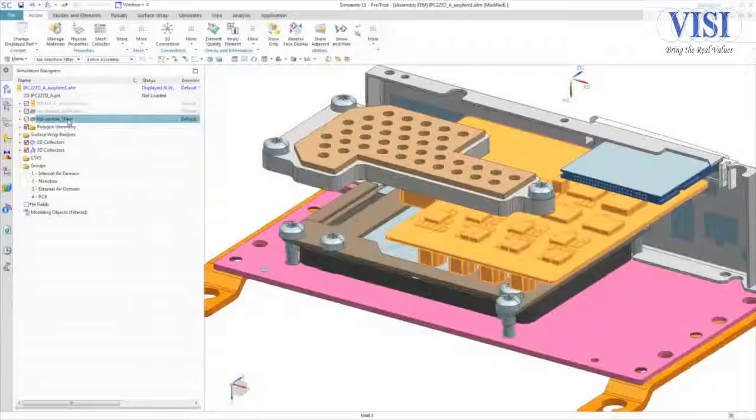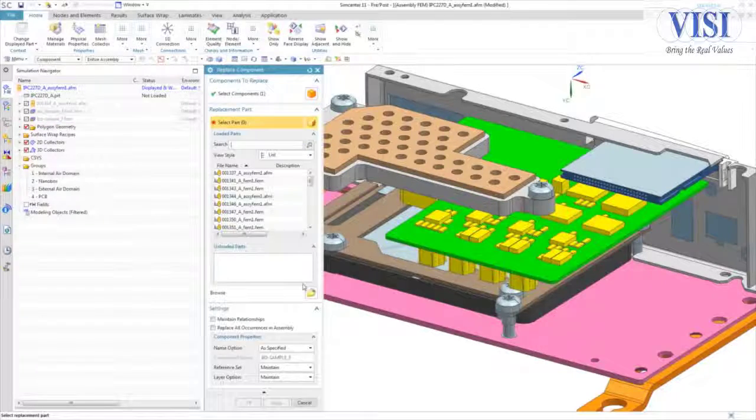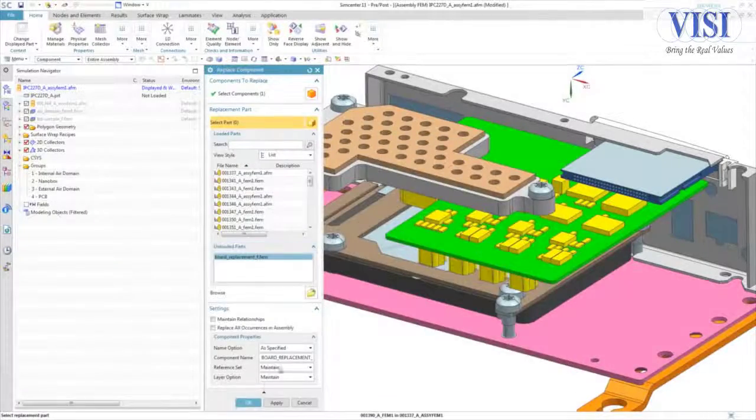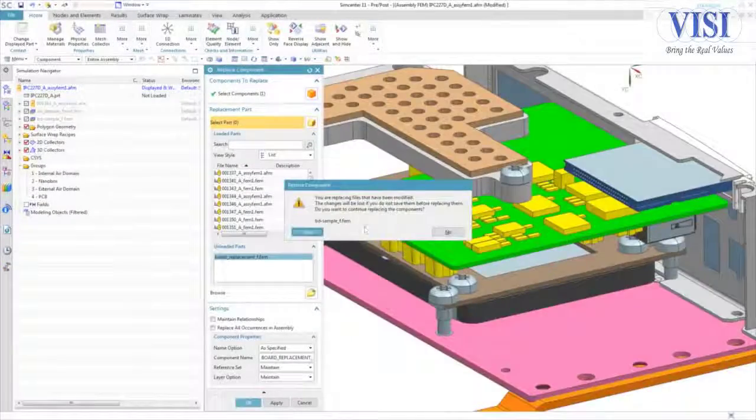While these results indicate the mechanical design will meet the operating conditions of this PCB, it is also possible to quickly create and evaluate multiple PCB design variants and compare the performance of each. With traditional CAE tools, this would be a tedious task that could take days, but through Simcenter 3D's fully associative analysis model, we can quickly update the analysis model to reflect each new design variant within minutes. Going back to the assembly model, we're able to replace a PCB component with a new board. When replacing the board, Simcenter 3D will automatically position the new board in the same location as the previous board.